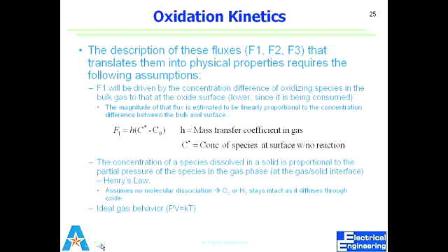You're basically overloading. If you apply too much voltage, it physically burns, so to speak. So I'm destroying these insulation layers? You are destroying the material, I don't know in what phase. It may not be the material in the device itself. You might just burn the interconnect, which may be metal that burns away. That makes a lot more sense.